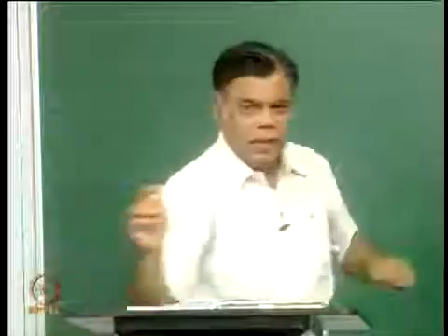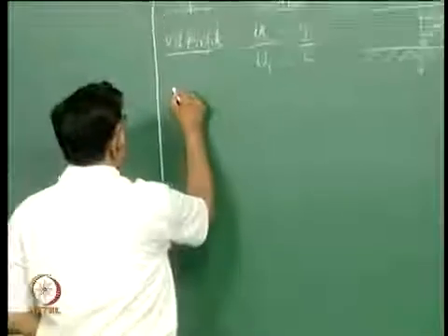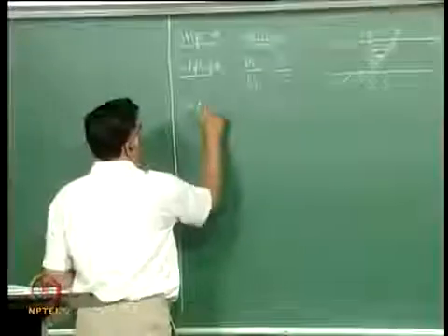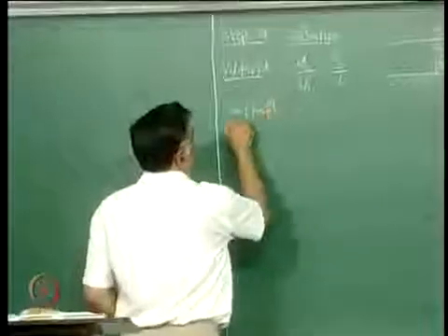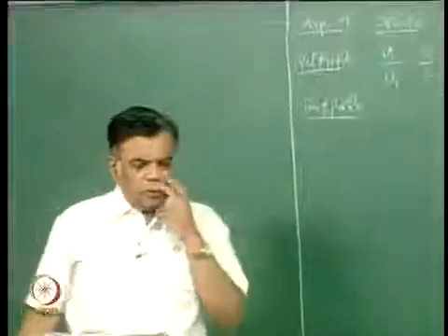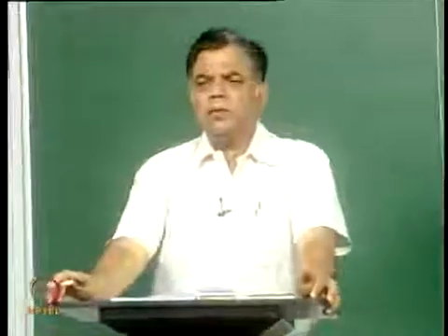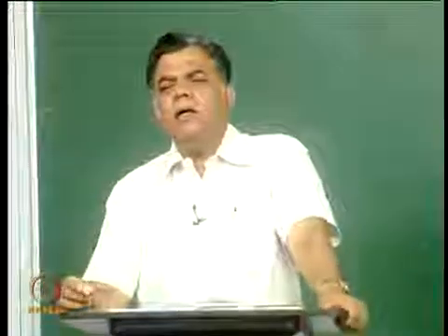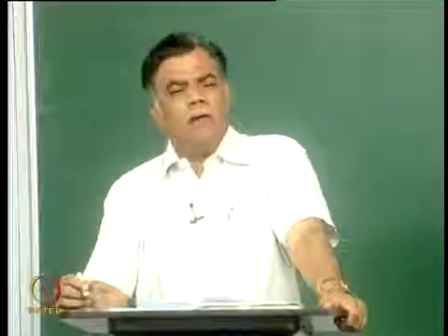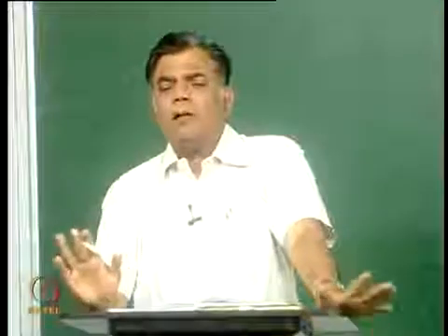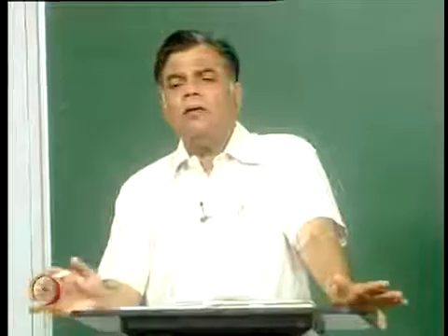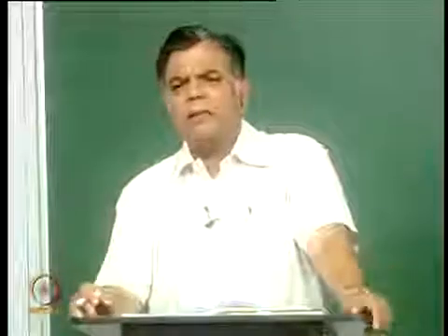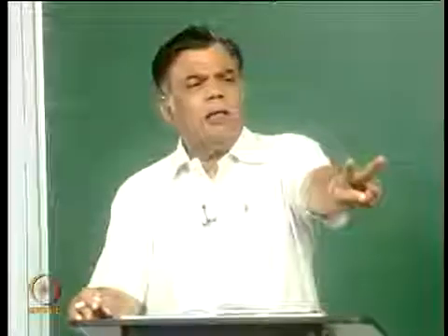The really exciting thing is go to the temperature profile. So write down the energy equation, d square T by dy square plus mu by k du by dy whole square equal to 0. Boundary conditions at y equal to 0, T equal to T naught, y equal to L, T equal to T1. We have not said what are the relative values of T naught and T1, leave it, let us see what happens later. Now we have to integrate this twice.